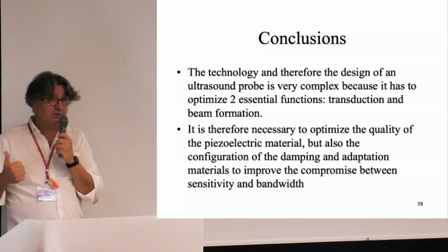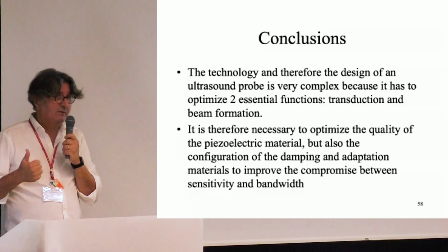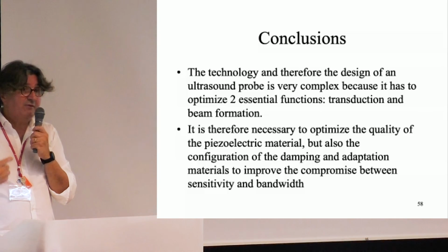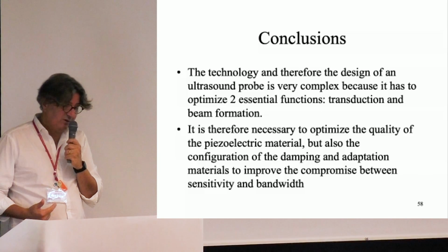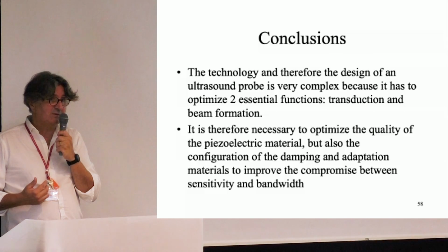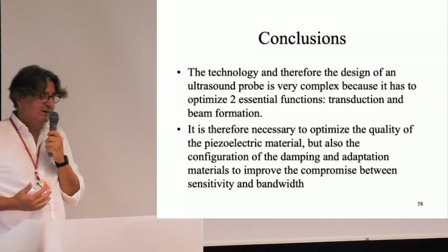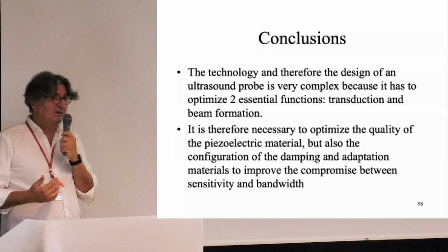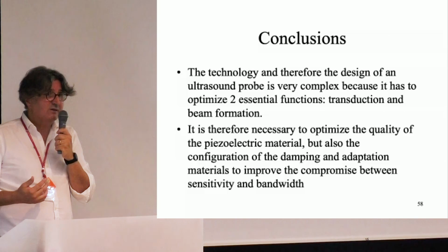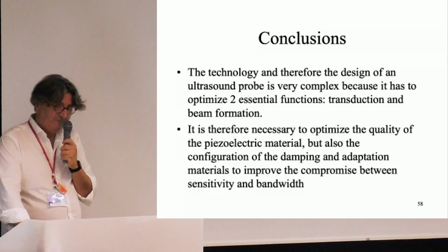This is why you have research on piezoelectric materials and on new transduction mechanisms, but also on the configuration of the transducer in terms of damping and attenuation, to improve the compromise between sensitivity and bandwidth. I think you have understood that you have to make this compromise, because high sensitivity means poor resolution, and low sensitivity means high resolution. So you have to understand that.